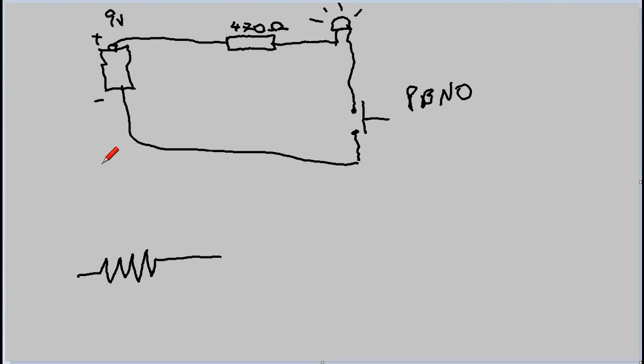This completes our circuit. You need a complete circuit for your circuit to work. And this is as basic a circuit as you can get. We could probably do a 3-volt battery here and eliminate the 470 ohms resistor and the switch, which would be an even more basic circuit. Let's actually do that. So here's another little battery coming off here. Now this one is 3 volts. And we have a little LED.